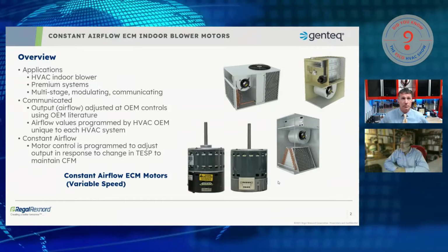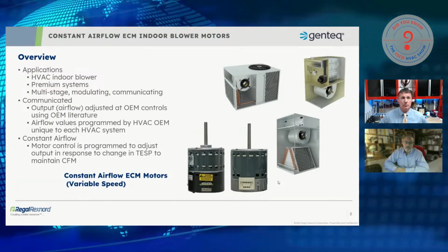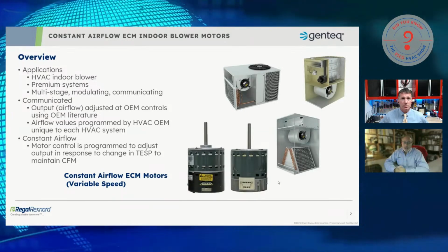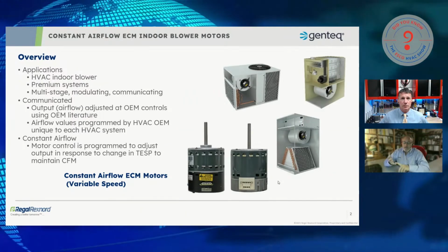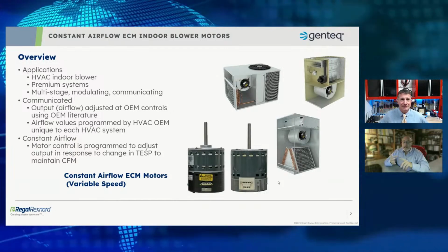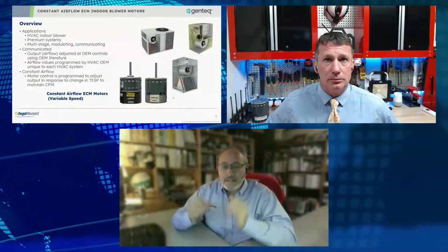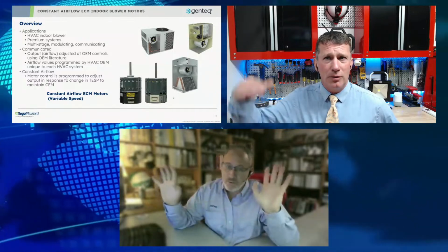So the last bullet point I did want to mention before we move on is the constant airflow programming. Each of these motors actually has a constant airflow algorithm, because that algorithm has to understand airflow in CFM, has to understand static pressure, and it has to correlate that to torque and speed in the motor. We're not going to dive that deep into the motor in this particular show. I mean, we could, but that would be a whole show unto itself.